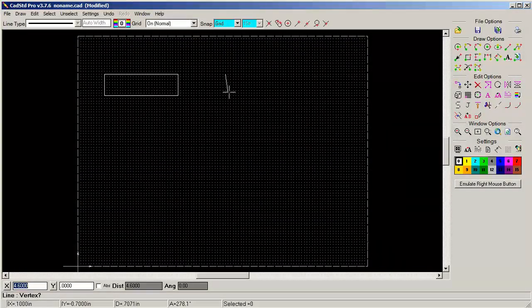Create another box to the right of the first box using the same method. Keep the top and bottom at the same horizontal lines as the first box. Make the width about the size as shown. This will be the side view. Create the next box, top view, below the front view. Limit its length to the same vertical lines as the front view. Make its width the same number of grid spaces as the side view.